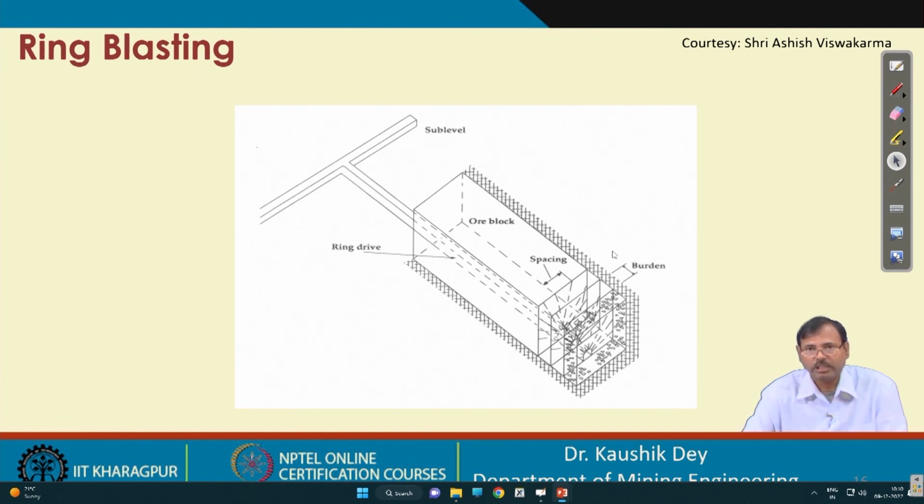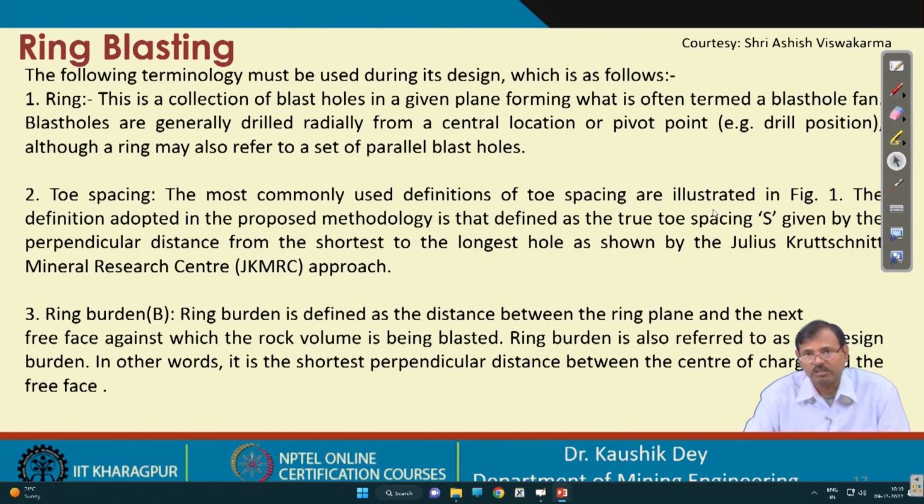So, a similar technique can be adopted here also, but once the slot is made, first when there is nothing available. So, when the slot is made the first time, that time it may be possible, next time onward the complete long holes can be blasted together, because the old slot will act as the free face to the new slot. So, that is the benefit of the slot blasting.